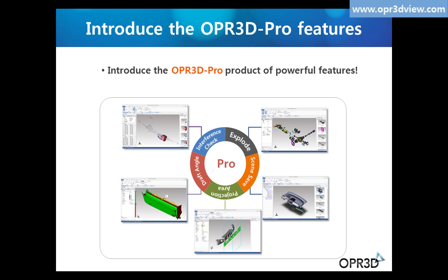The fitting bound box function is for measuring the outer dimensions of a tilted model without changing the reference axis. The draft angle function measures draft angle conveniently, and it can display angle by color, and the undercut determines the angle and coordinate immediately by using the mouse.